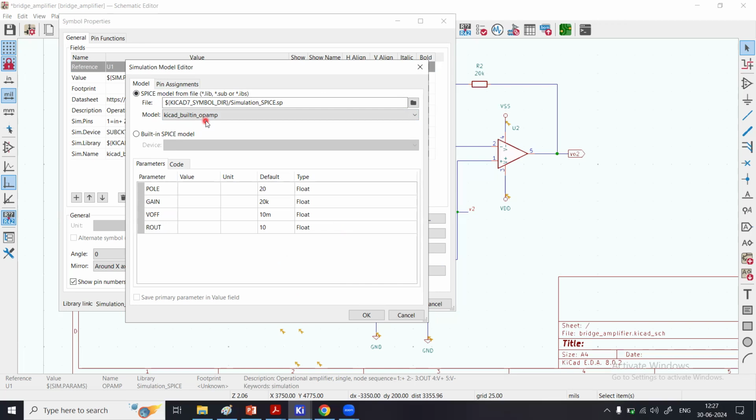However, if you want to use the manufacturer-provided IC for the Opamp to have a real-world design of an instrumentation amplifier to process signal from a strain gauge sensor, you can do that by Googling a specific SPICE model for the Opamp IC, then downloading the SPICE model onto your computer and then calling it right over in the file. We have covered numerous modules on how to do that in earlier modules. So you are encouraged to go back and refer to those modules.